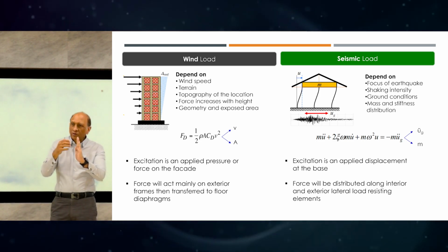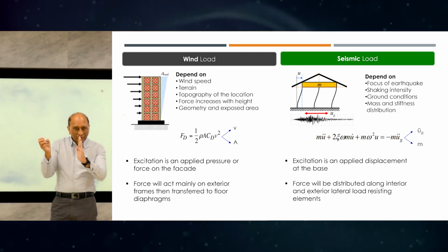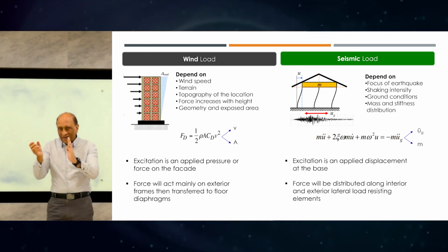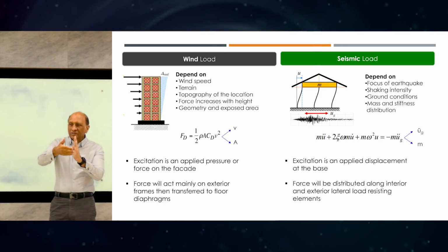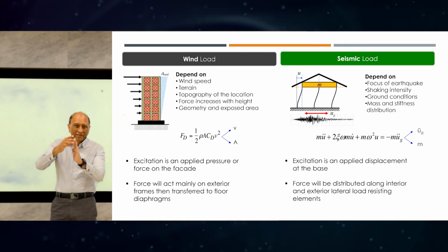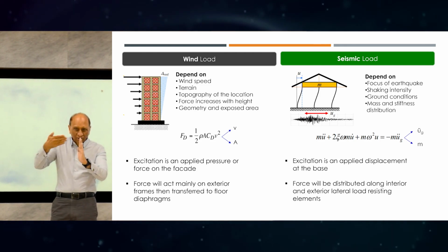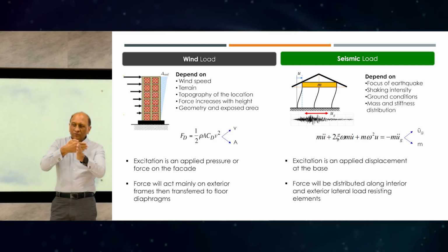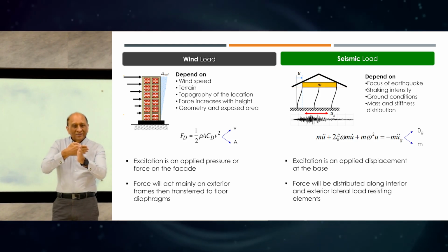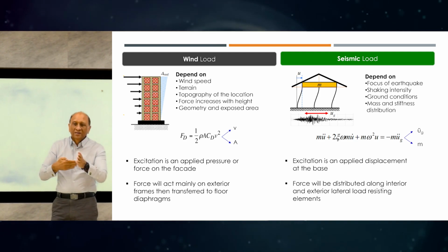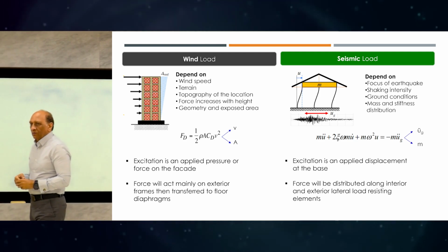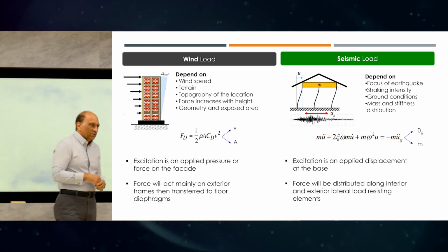And also, there's something called vortex shedding, because wind is not constant. Wind is blowing slow, fast, slow, fast. When it does that, the pressure changes on both sides unequally. So the building starts to move in that direction. Even though wind is in this direction, building starts to move in the opposite direction. That is very dangerous. So we have to prevent this crosswind movement, or crosswind oscillation, of the building.